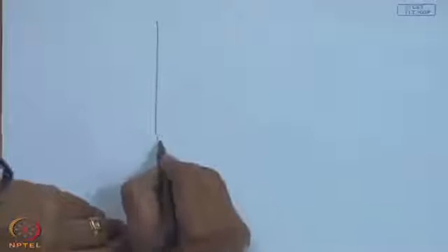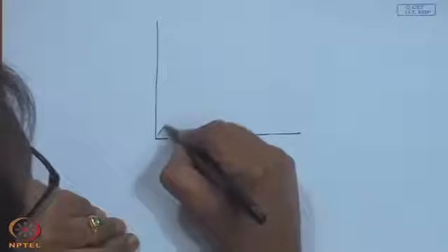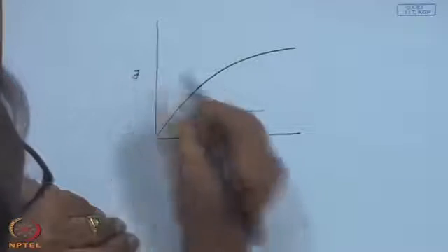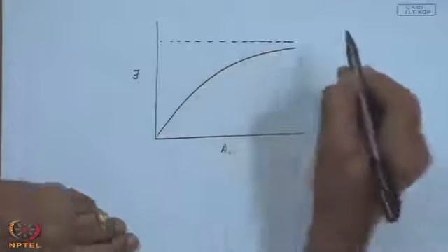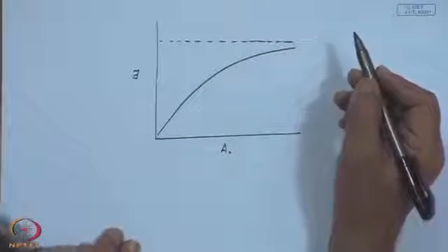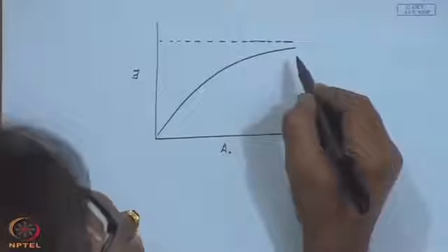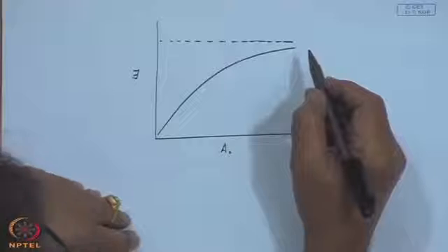If you have got 16 gigajoules of load, how much area do you have to put? We have already given sufficient logic to say that the performance is not linearly proportional to the area of the collector, but it is monotonically increasing with a negative second derivative, a convex upwards curve of this particular form. So, if I plot the solar load fraction F versus the area of the collector, the main variable, of course, this curve depends upon the type of the collector, performance, location, then the parameters that you choose, etc.